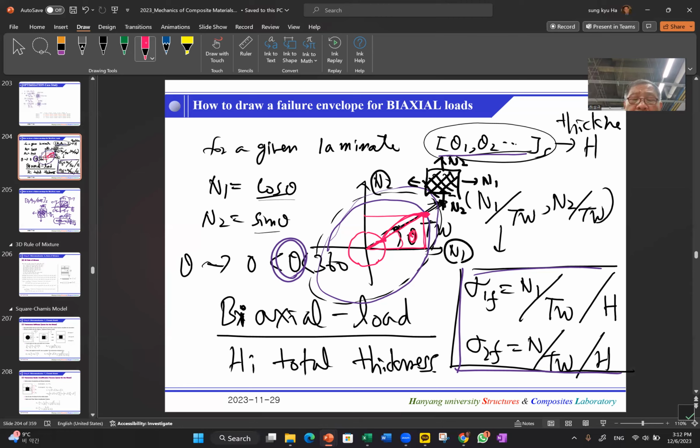And for the given theta, now we do the same thing. We have a different ratio theta, and then we find the safety factor, and then we increase the point by increasing the radius by the factor of the safety factor. So we iterate, we do this at that point and that point, and we keep doing so and generate the full failure envelope. Again, this is very useful.